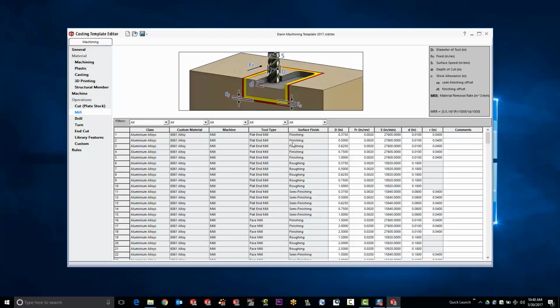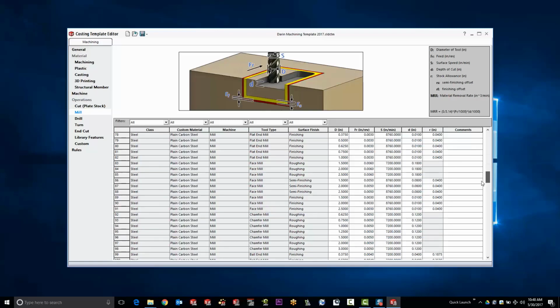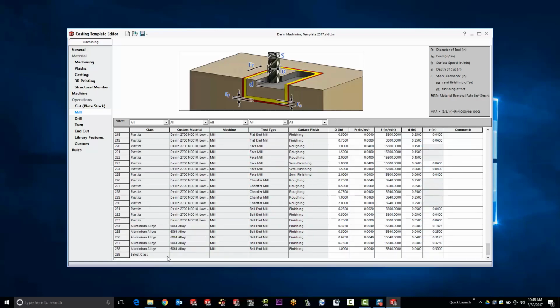So this is essentially like setting up machining processes where, based on physical geometry, it will either match a drill type to a hole, or if it finds out that it's an odd size hole, it will have to do a rough and then finished pass, again, based on the tools that you do have available in your machining centers. So that's going to give us the most accurate representation of the costing values. Once again, all the way to the bottom, you would be selecting from lists you've already created, material lists that are specific to that previous list.